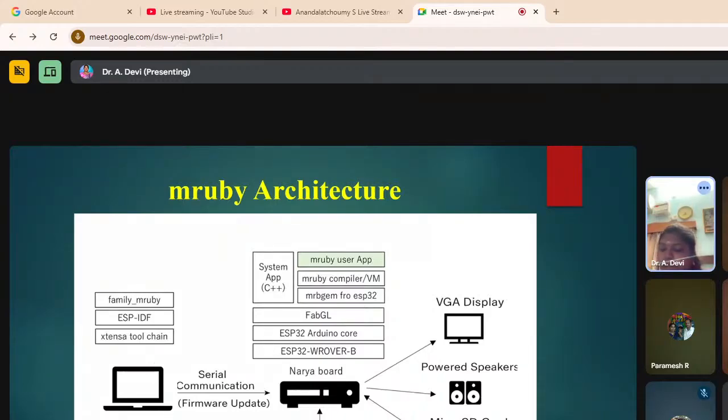That's where the Espressif toolchain, which is available on the desktop computer, comes in. It provides the compiler, linker, and debugger needed to build applications for ESP32 chips. On top of that, we use ESP-IDF, the official IoT development framework for ESP32 devices.